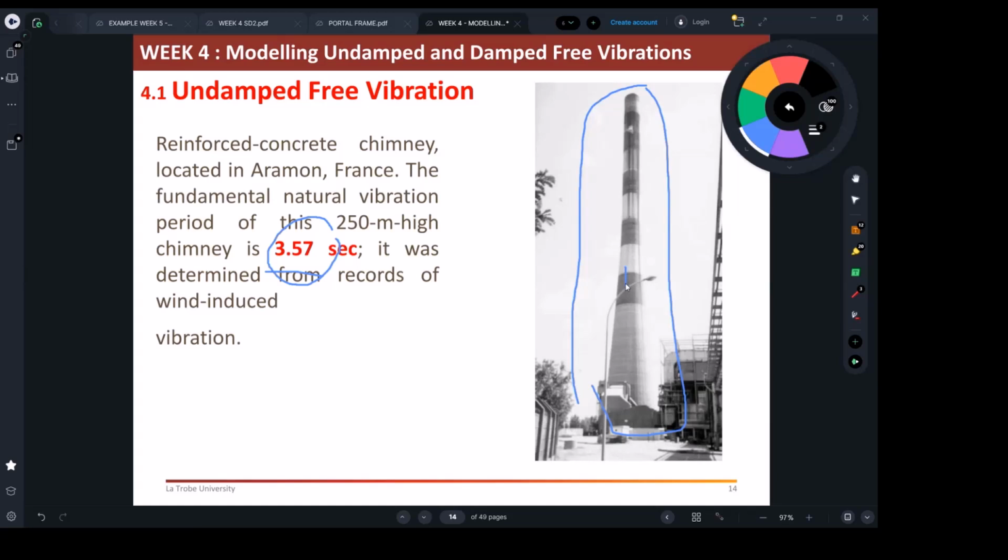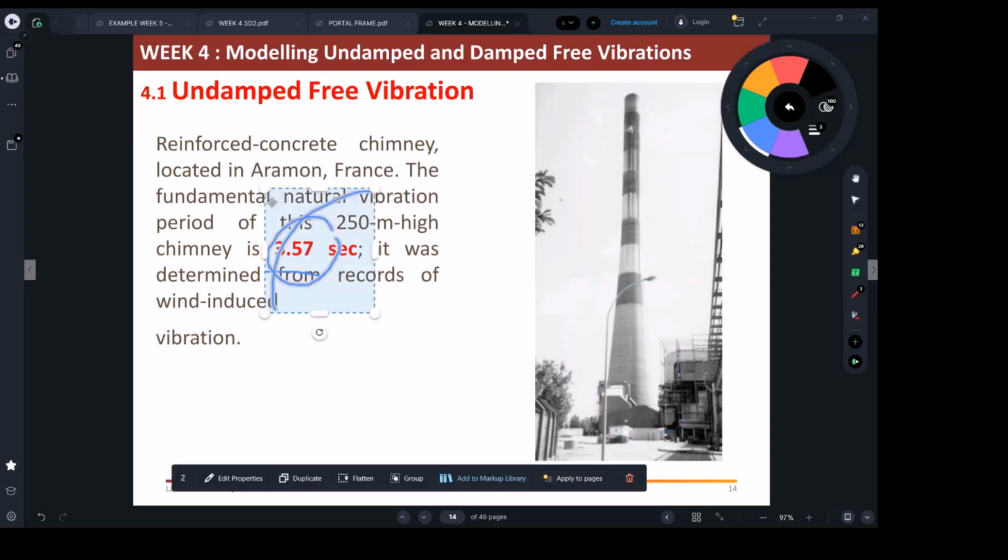So how do we make sure? We have to do a test, because it's going to tell you what the actual K is. If you found the actual K is way, way below what the ideal non-damaged section is, then you can say to council, be careful. The test showed us the stiffness is way less than expected. So that's really how it works. Questions?